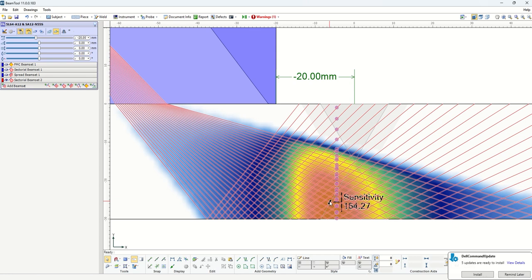But if our goal is to cover this well, I have the confidence to say that we reached our goal of improving the sizing along the bevel by using a focus. So this helps us know that although we are dropping sensitivity, this shouldn't be a factor that stops us from using focusing, because of the advantage in sizing and sensitivity we get.